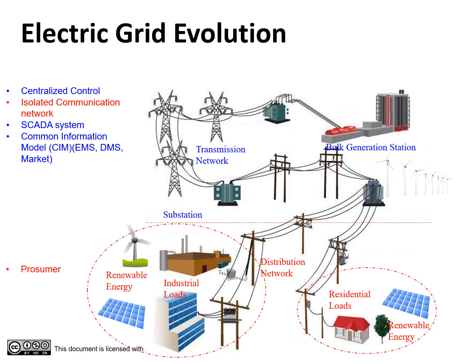Integrating renewable energy with a conventional grid based on centralized generation and central control is challenging. The renewable energy is distributed by nature, which means most of the renewable energies will be integrated into the distribution networks. Integrating renewable energy into the distribution networks will lead to a two-directional power flow, which requires modifications of protection algorithms.